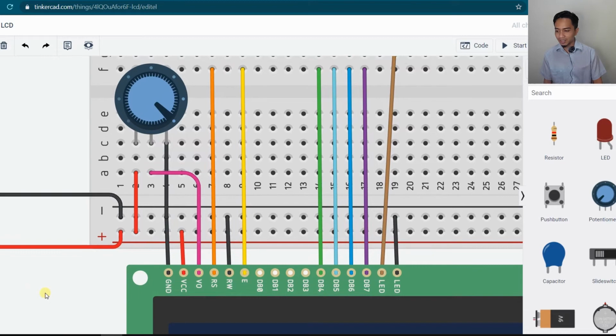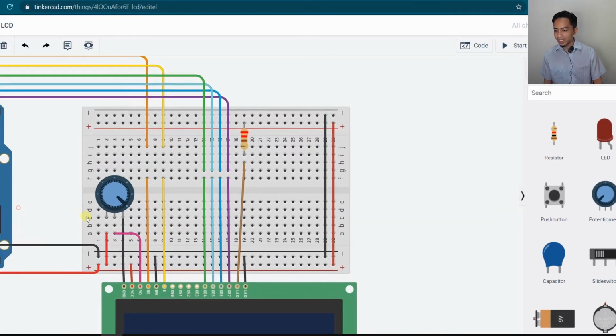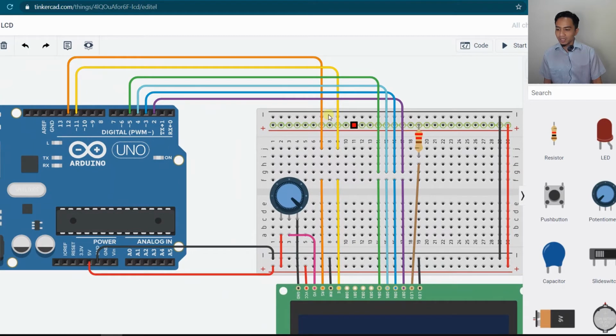But as you can see here, this is for those who get this kind of LCD display. You can see we need 1, 2, 3, 4, 5, 6 pins. So with 4 bits of data, you need 6 digital pins just for this LCD. If you have a button switch, digital sensors, or any LED, you might have already used all of these ports, which means the ports on this Arduino might not be enough for your project. And that's why I don't usually use this LCD here,